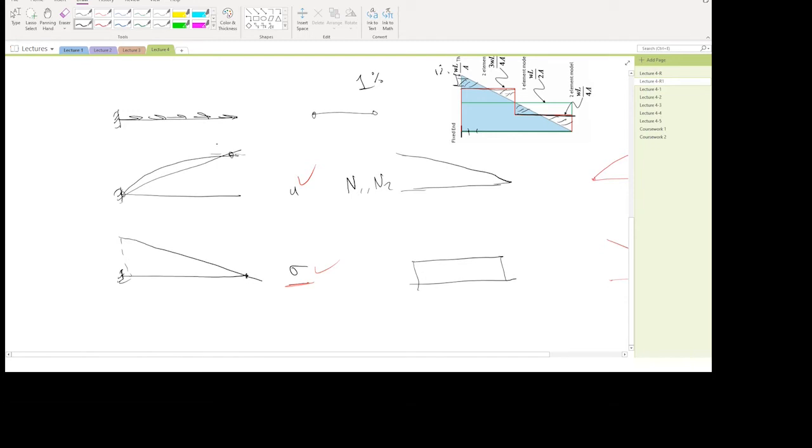So this is not quite a constant. I probably just draw it with a constant. We'll try to interpolate this using a constant. Now, this will result in a huge error in the stress, not very bad error in the displacement, but in the stress, you produce quite a lot of rubbish if you want. I mean, I would describe this result as rubbish.